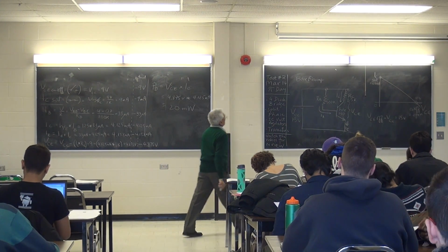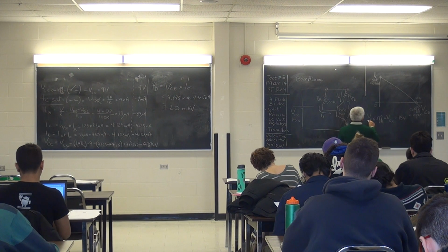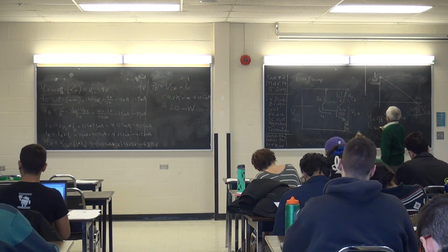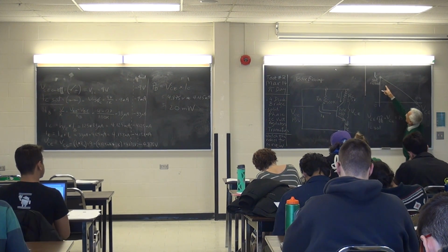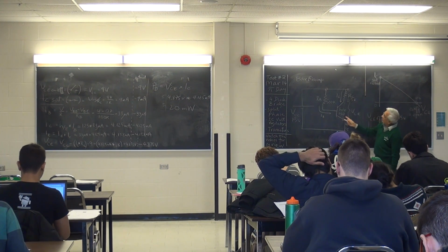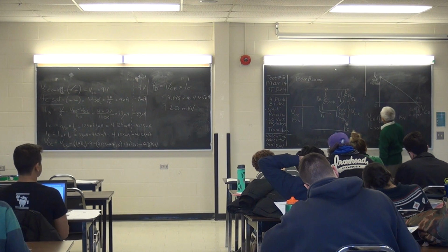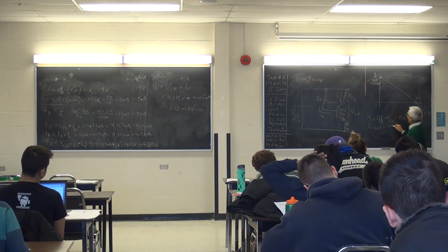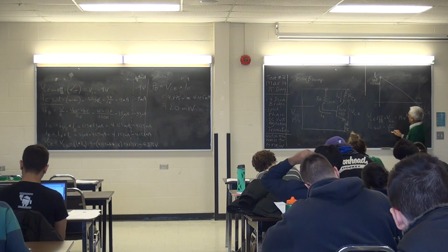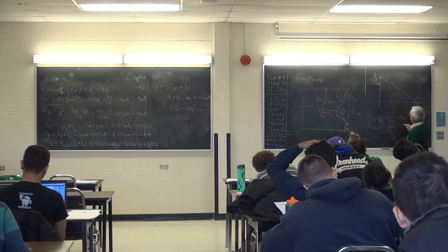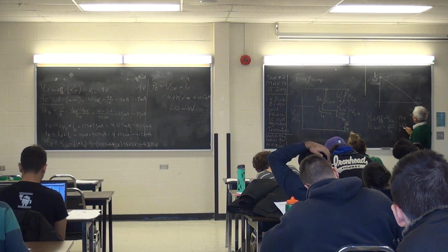Saturation. IC sat. That's when the transistor acts like a closed switch. If it's closed, okay, that voltage, resistor, and that's it. So VCC over RC. 15 over how much? 1.5K.